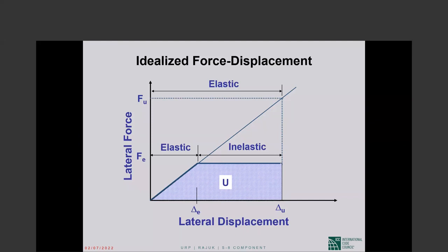We don't need a high degree of inelastic deformation capacity. Seismic design is always a two-part affair. Design for the forces that we have chosen to design for, the strength level, and detailing for the inelastic deformation capacity that we must have in order to be able to design for the force level that we have chosen.